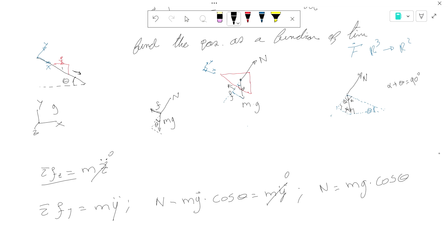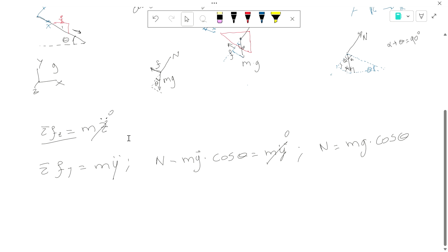Okay, but this is interesting because remember that the friction force is equal to the friction coefficient times the normal force, right? Remember that this is how we characterize the friction force: the coefficient of friction, which is just a number between 0 and 1, it's a percentage, times the normal force. For instance, for a tire made out of rubber on a dry street, on pavement, it is around 60%. So the friction force is about 60% the weight of the car.